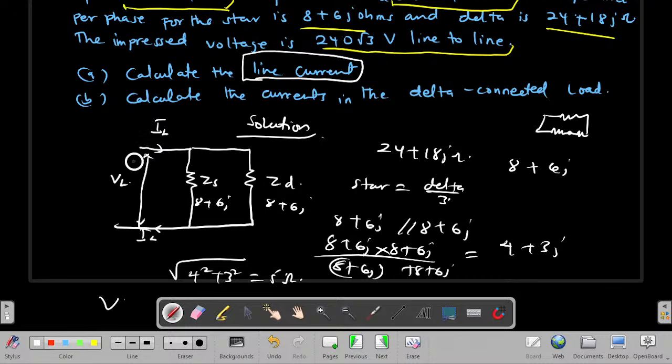That is what I indicated here, that between this line and between this line, I have 240 volts. Okay. Now, for me to simplify this, remember that from the beginning, we converted this to what? The star configuration. And remember, in star configuration, your line voltage and your phase voltage are never the same. That is one thing you should take note of. Your line voltage and your phase voltages are not the same.